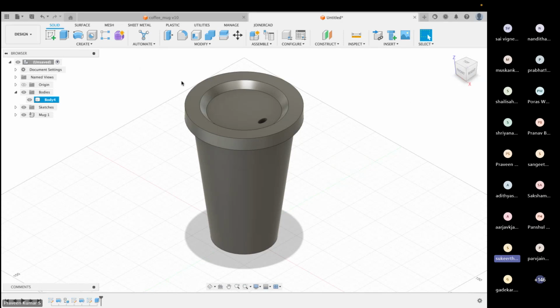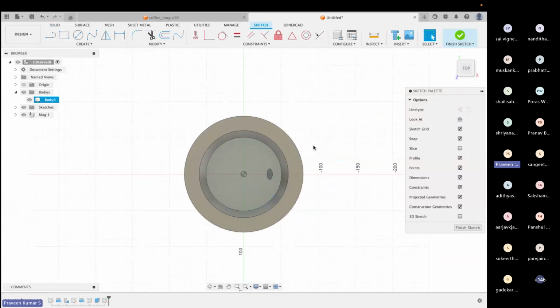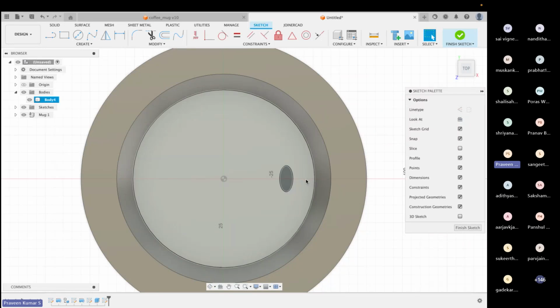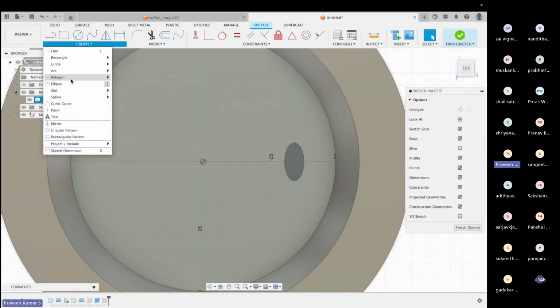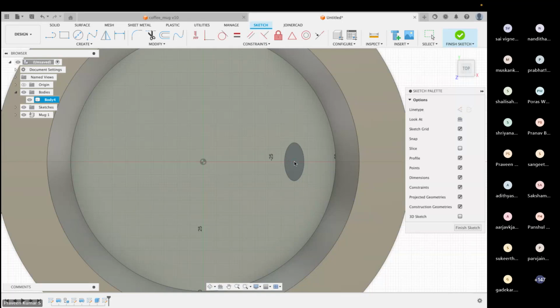Yeah, got it. Thank you. Okay. Now, again, we're going to make another sketch. We're going to make an upward zipper now. So on the same plane, create another sketch, and on the same ellipse, we're going to create another one. So go here, click on create ellipse, find the center. The center should be coming as a circle for y'all. So the center should be here, and then again give a dimension of 15, click, and then 7.5, click, and then you finish sketch.